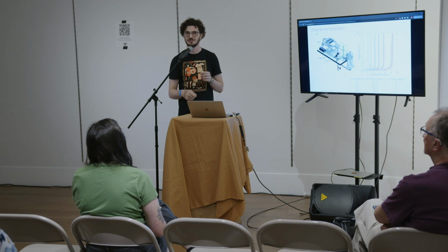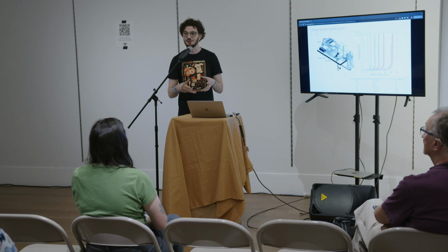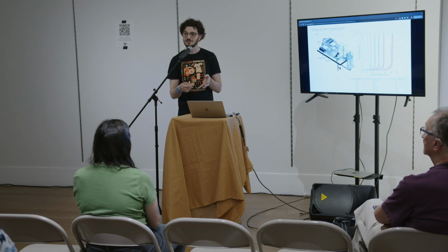So we ended up having to, you can use a thickened acrylic solvent where they dissolve some acrylic in the solvent and it's all goopy to try to fill in those gaps, but it gets really messy and difficult. Or you can use RTV silicone, which is what we ended up doing, to just fill in the gaps and slather over the problem. Yeah.